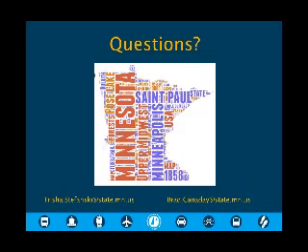Has your contractor used control points at all in the data collection process? For the scanning, yeah. Where we needed the Type 10 models for design and stuff, the contractor subcontracted that out to a surveying firm to get the targeting done. And I did see a targeting question about what type of target we use. It depends on the vendor. Some of them like an X, some of them like a chevron pattern, and then the orientation varies with each one. So you have to deal with each one of them.